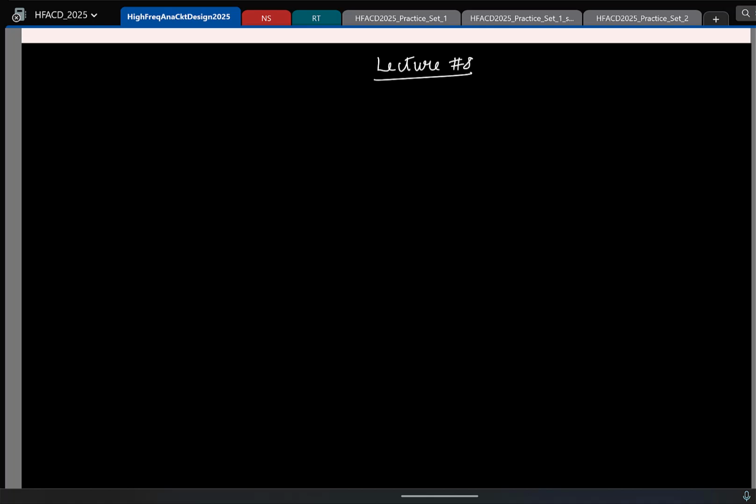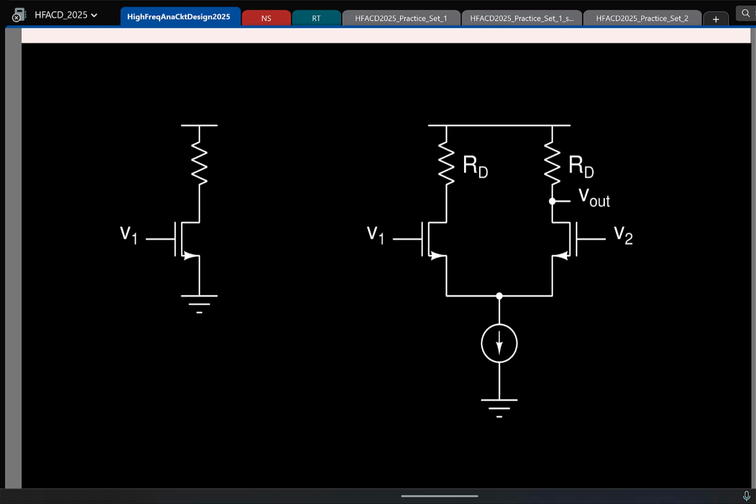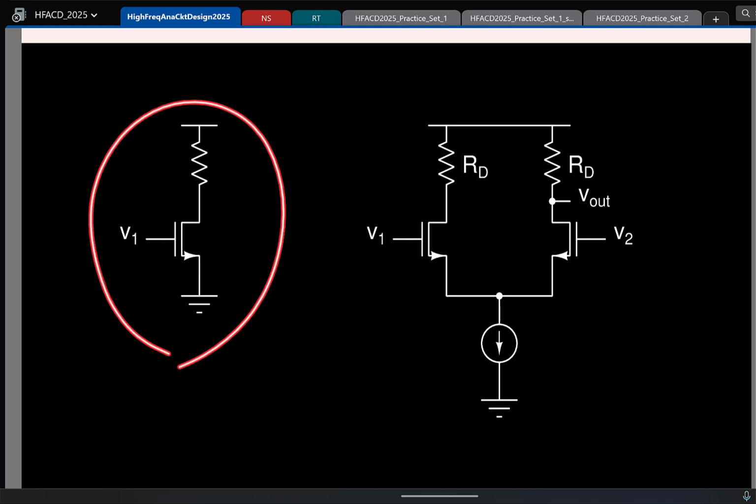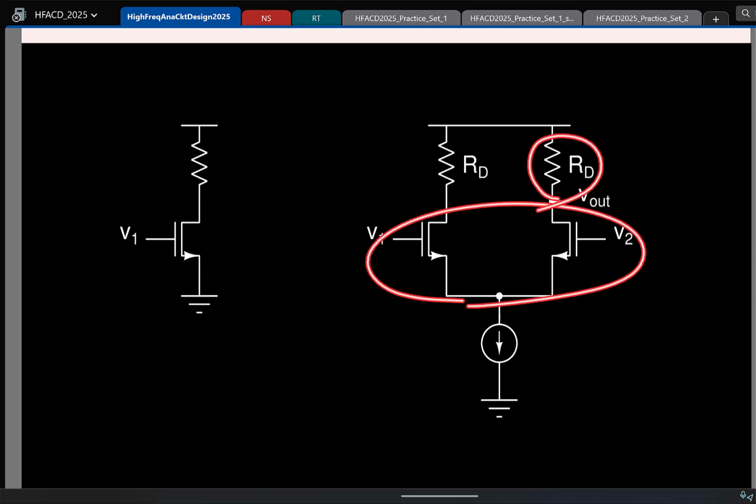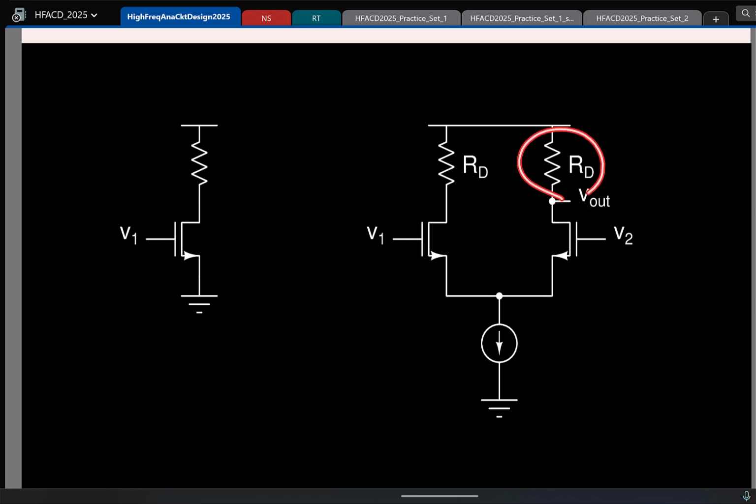Okay, cool. So to give a broad recap, so far in this course we did the following. Our goal was to design an amplifier or op-amp that has a very large gain. So we started with this simplistic structure, then we converted it to a differential structure like this, and here the gain depends on the gm of the transistor and the RD. Now to increase the gain, we wanted to increase RD, and ideally we would want this to be an open circuit in small signals. So ideally what would you want to put here? A current source. Incrementally it should be open. So that's what we did.